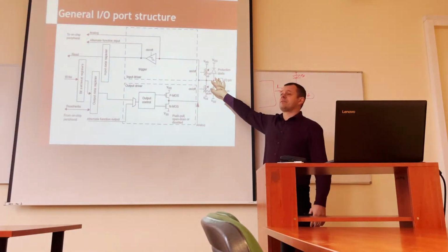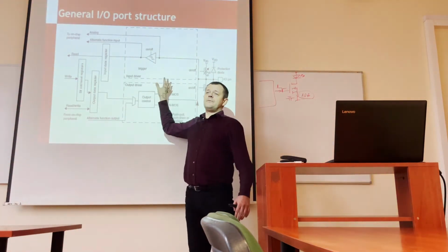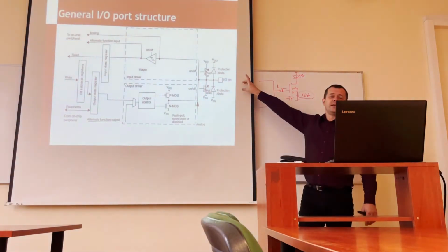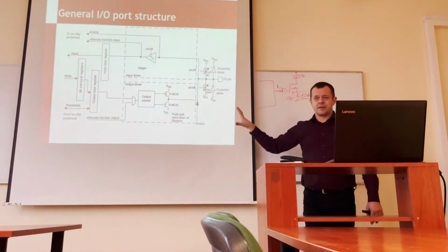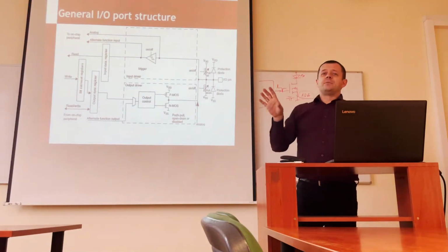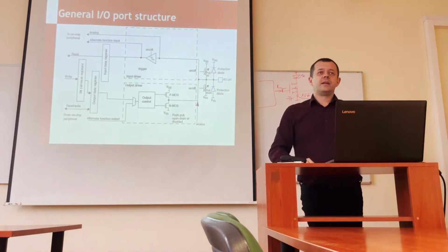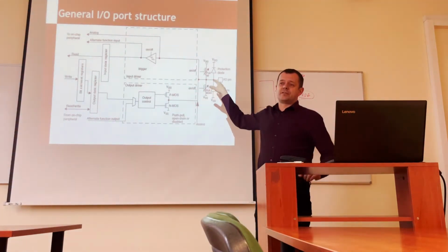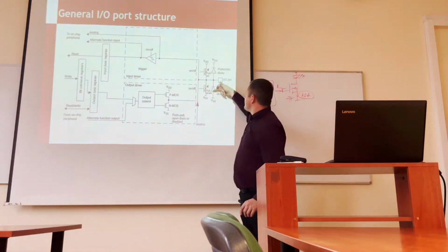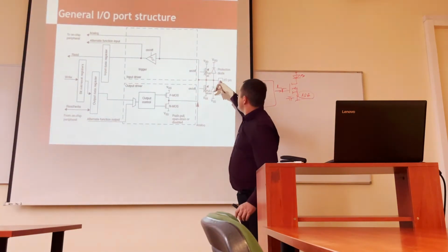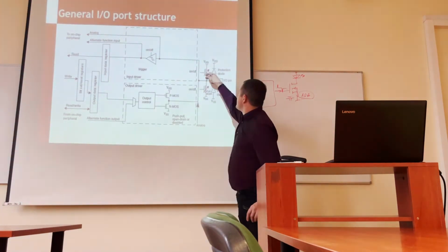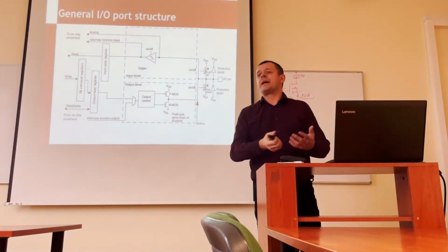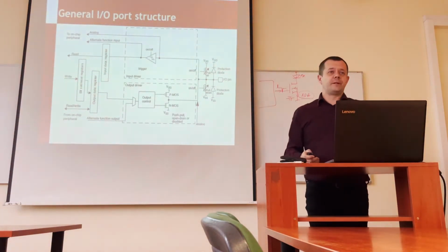So very often the port stays functional if we exceed the voltage, but we break down the current through these diodes. That's actually what's happening, and that's what you can expect. How can you observe it? This part is heating. Of course, the whole microcontroller starts to heat because there is a current flowing here or here, or somewhere here there is flowing current even with no signal connected, when you break the microcontroller, when you break the pin.